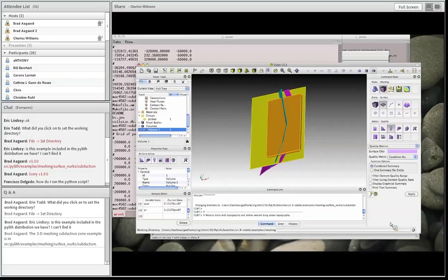Well, it could be if there are curves that already existed. That would create errors because the curve IDs are hardwired into the journal file. So first thing, do a reset. Make sure that reset also deletes all of your Apropos variables. It's remotely possible that there's some conflict there.